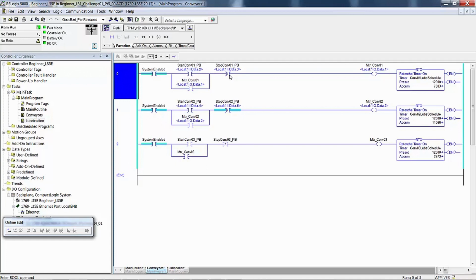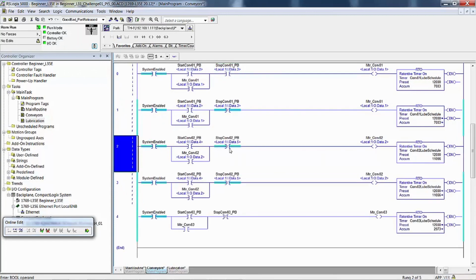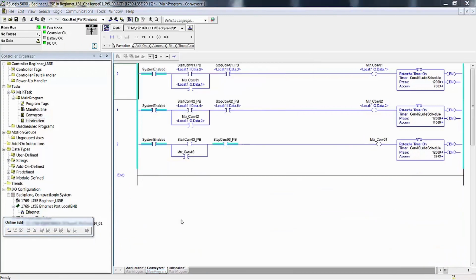Well, we don't want normally open like that. That's normally open. We don't want normally open. So I'm going to change these back. Edit mode. And this one I'm going to change back because the logic isn't going to work correctly, because remember, we have specialized logic. That is why I was using normally open here, and then I would just turn on input 3 and 5 to simulate stop buttons that were normally closed.